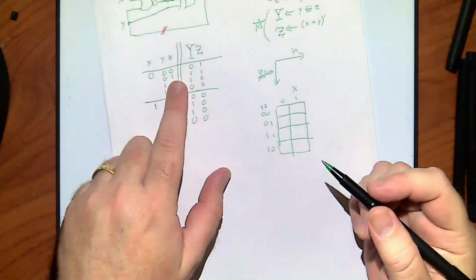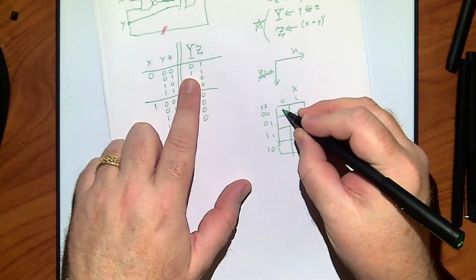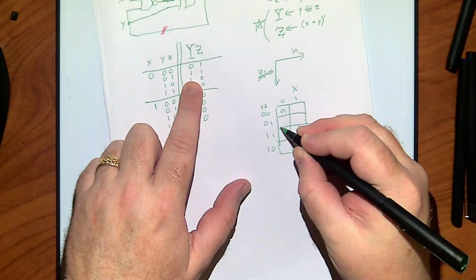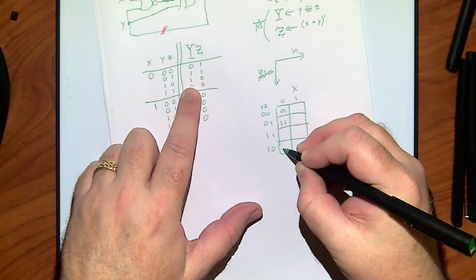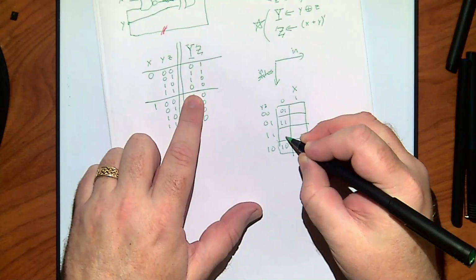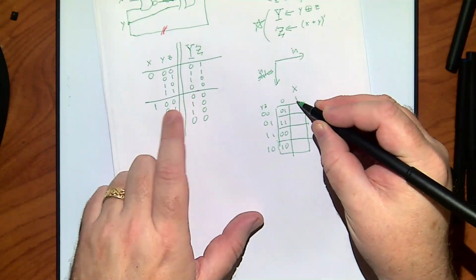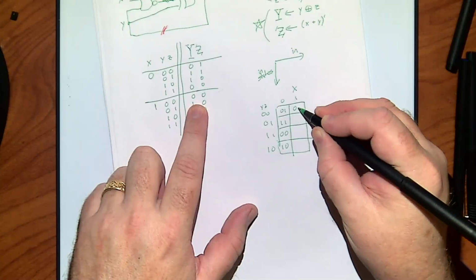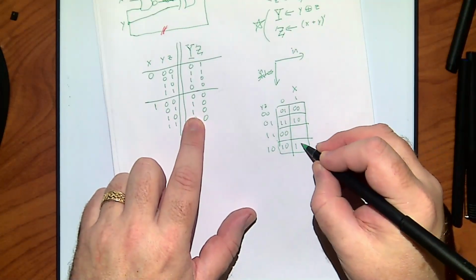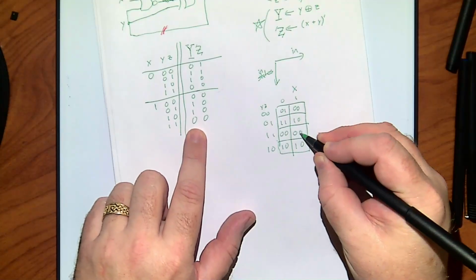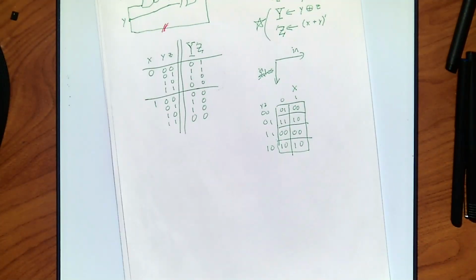All right. So now I can copy them over. I'm going to write the 2 in here. So we just write them in 0, 1, 1, 1. Now remember, when it goes here, it drops to the bottom. 1, 0, 0, 0. And then the next one, I'm now in x equals 1, 0, 0, 1, 0, 0, 0, 0. So remember, we just have to flip the last two to go into gray order.